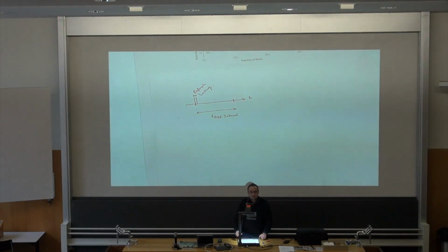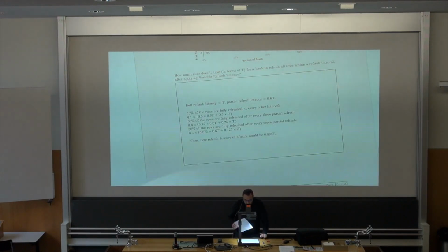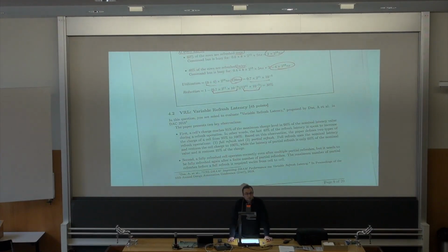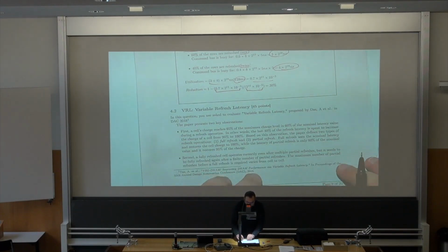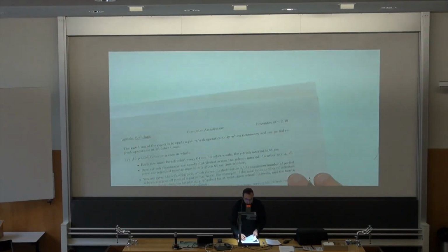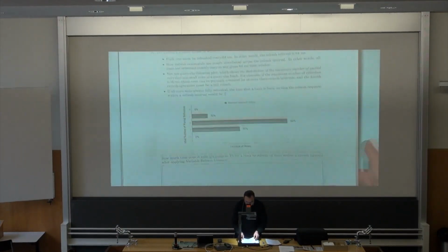And this paper tries to mitigate this refresh latency, and the main observation was that you can actually get a pretty good restoration in the voltage level if you just wait for 60% of this latency instead of waiting the whole thing. So the remaining questions are going to be based on this observation.